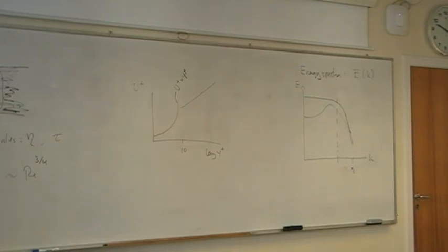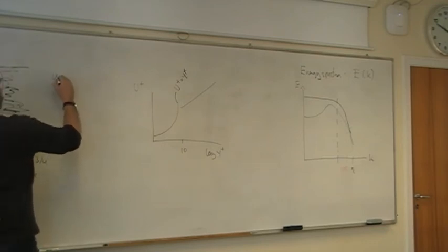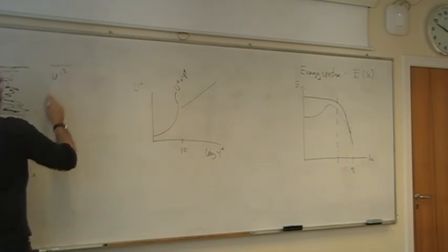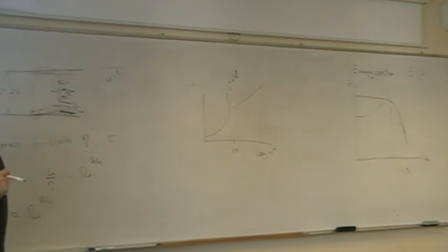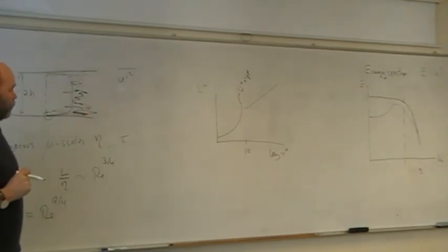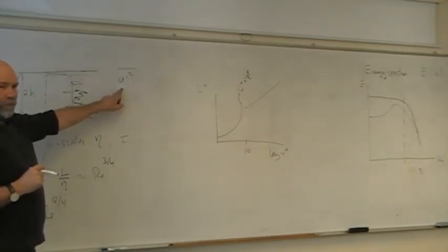Well, for this test problem, you should create this average velocity profile fairly easily. It won't be hard. But I'll show you when you look at the higher order, that's where you run into problems. You start plotting this one, u prime squared, time averaged. Not so hard. This will be sort of a part of the k in k-epsilon.